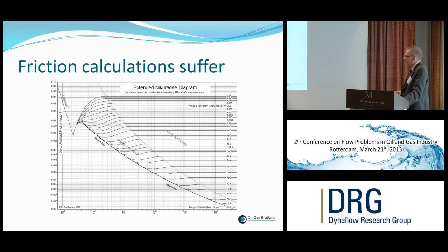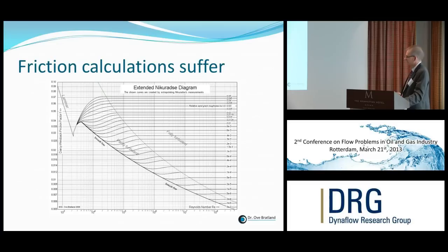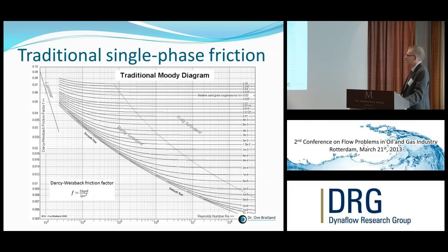But the diagram engineers have used for 30 years doesn't look like that. It looks like this. Do they compare? Does it look the same? No. So what we have done is we have said, okay, we use the same as Nikuradse out here. And then we just think Nikuradse was plainly wrong up here, so we do something completely different. And then we curve these in a very different way than any measurements have ever shown.